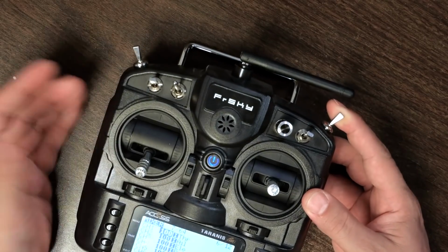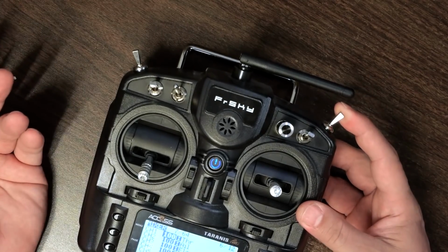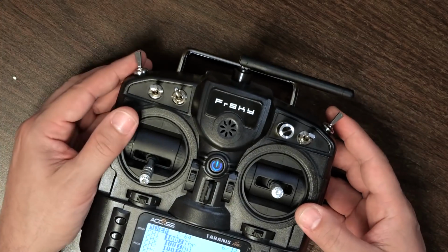When I pull this switch, the beeper will go beep, beep, beep, and when I pull this switch, the pre-arm mode will become active and I can arm the quad. Those two things can happen at the same time. That's okay. And in fact, it's kind of nice that when I pull the switch to pre-arm, the quad goes beep, beep, beep. Oh, you're about to arm. Are you sure? I don't know.